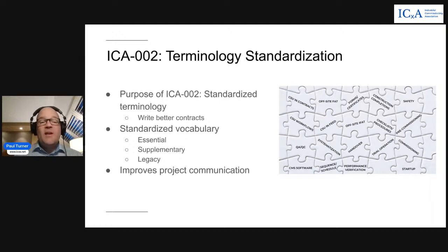Another term, actually, believe it or not, is the term commissioning itself. The term commissioning itself has created lots of confusion because the term commissioning itself doesn't really mean anything. It needs a qualifier, right? When people use the term commissioning, are they referring to testing? Are they referring to the commissioning process? Are they referring to the phase of testing after static commissioning and before startup of the project? And I hear the term commissioning used on projects, and I can see that people are not talking about the same thing. So the term commissioning on its own isn't actually very helpful either.